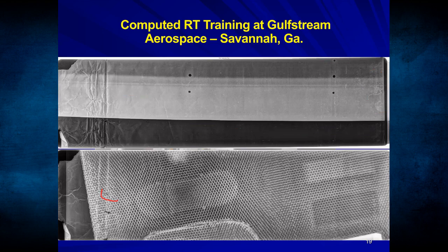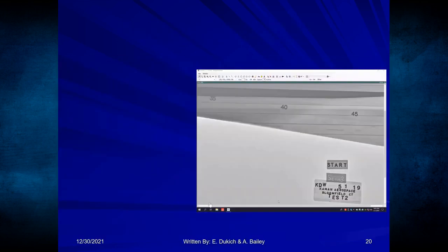But we also have some holes, and some of the core is splicing a little bit, and we have some wrinkles over here. Now this over here, this is normal. These areas over here, that's normal structure. So as an NDT person, you have to know the difference between what's acceptable and what's not acceptable.